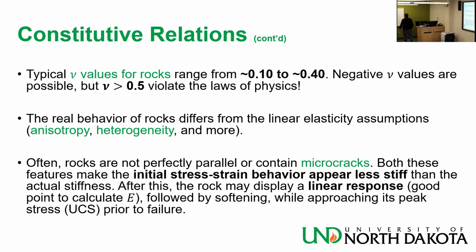Let me explain what I mean by this. If I have a material that has a lot of cracks in it, a lot of pre-existing failure planes, and I start compressing it, those microcracks are going to close first.